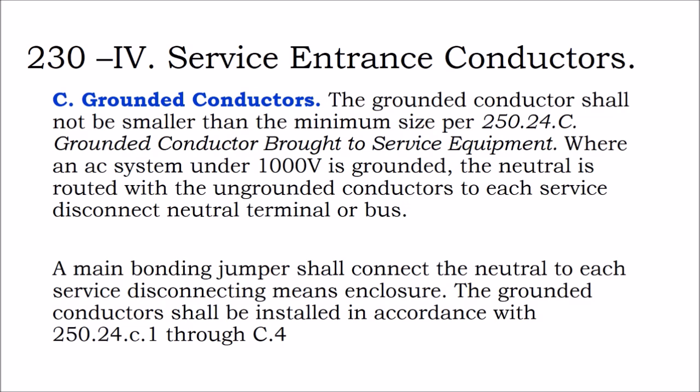So it may be further up the utility line than your electric service panel. So you're not connecting neutral to ground in your electric service panel. But if you're establishing a new electric service, you still might need to provide a ground out by the transformer for the utility to connect into.